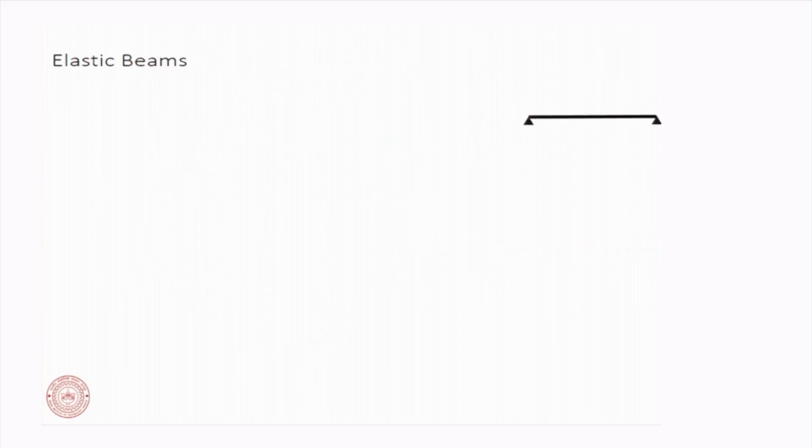Now, we can extend the same analysis to elastic beams. In the case of elastic beams, a beam is something like this pen over here. It has a thickness, and the thickness cannot be ignored. Unlike a string, a beam, say a cantilever, has a thickness dimension which is not infinitesimal compared to its length, and a plate is a two dimensional extension of a beam, in which the thickness cannot be ignored compared to the x and y dimensions. So, the z dimension has some considerable thickness, due to which our energy term adds up to something else. Okay.